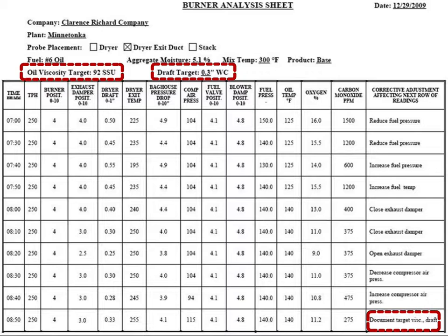Notice how the dryer exit temperature had changed from 225 degrees to 255 degrees and the burner position had remained the same. True story. Natural gas. Burner control and damper control was placed in manual. Exhaust fan damper was adjusted for more air and the mix temperature went up 20 degrees. The air-to-fuel ratio was excessively too rich. Adjust to your controls and pay attention to your instrumentation.